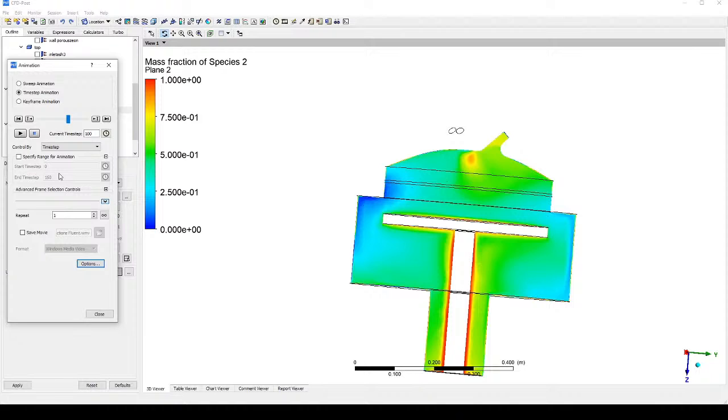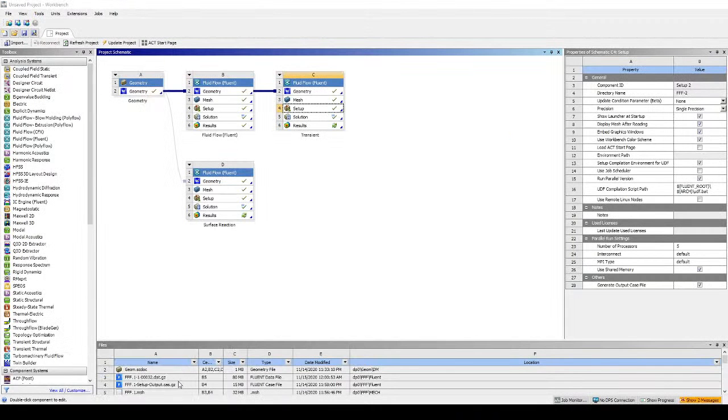You can control the mass flow rate into your system. You can specify the time that it goes in. You can specify the temperature of all the walls. You can try out different types of chemical reaction rates. And at the end of the day, you get production of deposition, and you can look at the thickness and the rate of deposition at different locations.